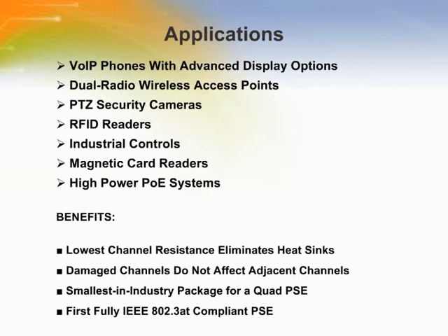The synchronous flyback converter provides a low part count design with the advantage that additional outputs can be obtained by simply adding windings. Synchronous rectification offers the benefits of high output power, increased conversion efficiency, and improved cross-regulation in applications with multiple outputs.